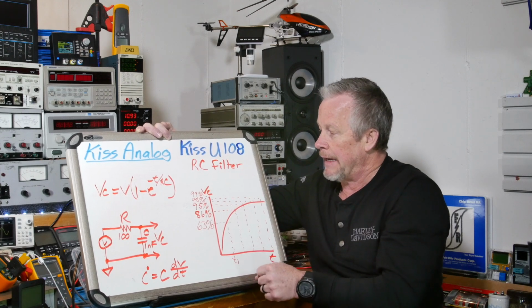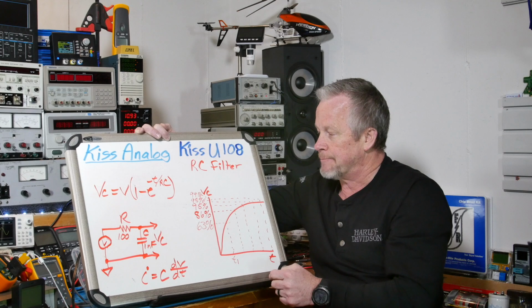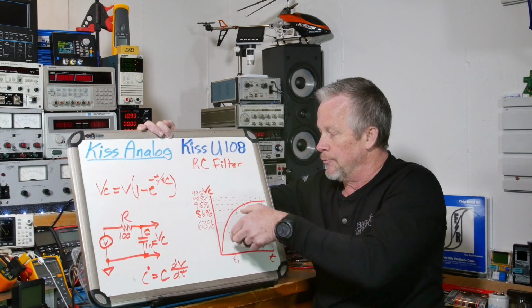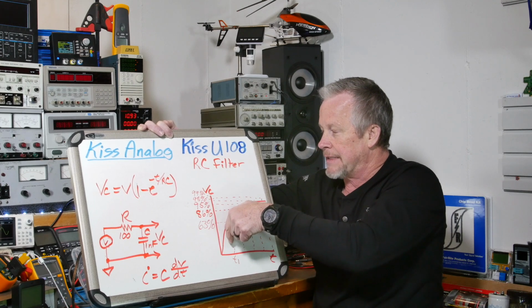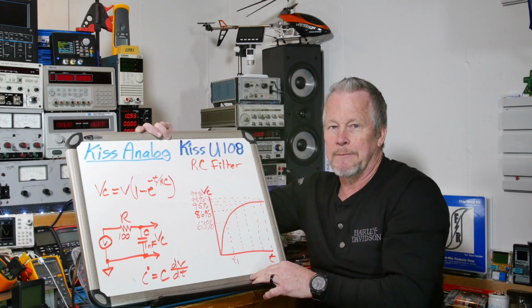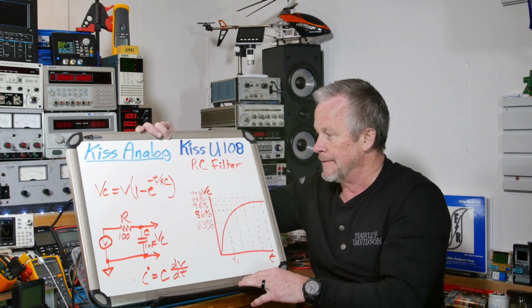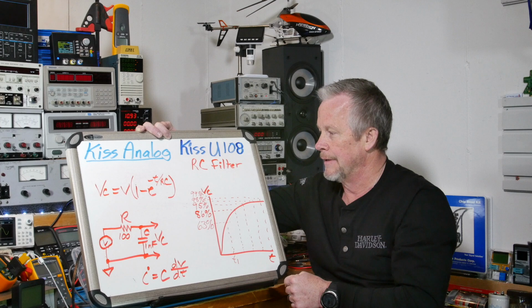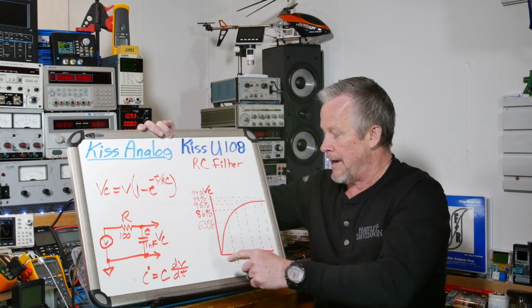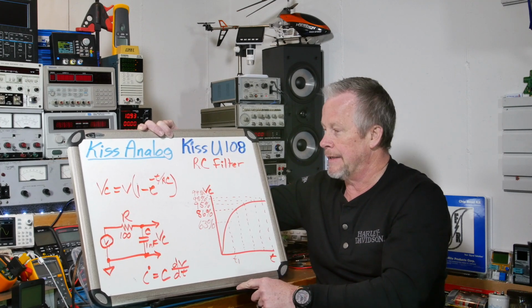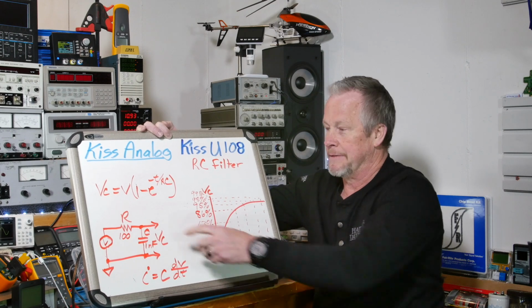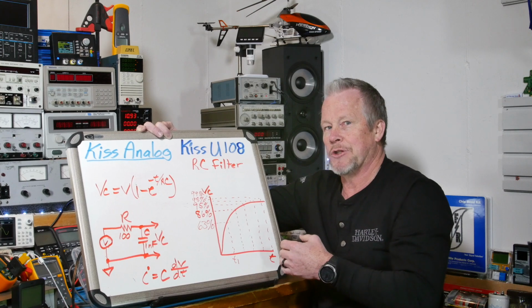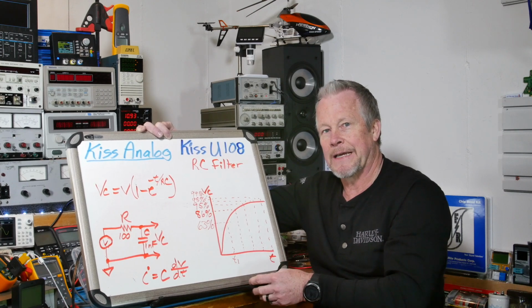Well, if you think about that, 86% at your 2 time constants, you're beyond that. So really, your rise time is within the first 2 time constants if you think about it like that. Okay? It kind of makes sense to correlate these things together. All right, so now I want to show you an example of a circuit that this exact thing would be used in, and it's used in just about every single power supply there is. Okay, let's look at that.